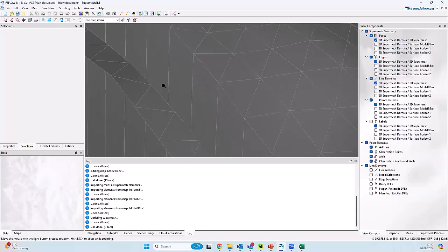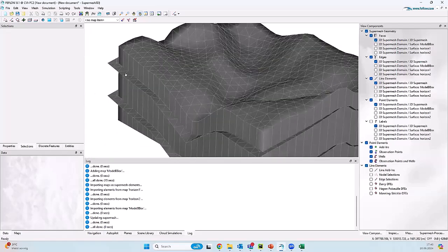it's very clear to identify the intersection. Sometimes you will try to make the surfaces fit exactly inside the box, and this could be a problem depending on the precision you're working with, especially if you're working with multiple software packages, like you do the box with FEFLOW, but the surfaces with Python. They might not match exactly, which could end up in potential errors, because if the surfaces are not touching, the technique that we have is not going to extrapolate the surfaces and force an intersection. It will identify a gap,